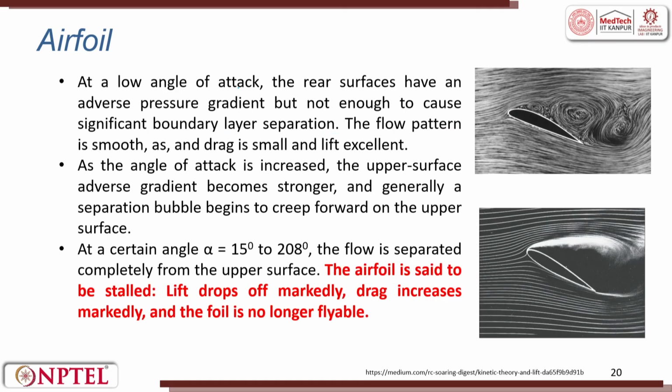At a low angle of attack alpha, the rear surface has an adverse pressure gradient, but not enough to cause significant boundary layer separation. The flow pattern is smooth, the drag is small and the lift is excellent at this angle of attack.